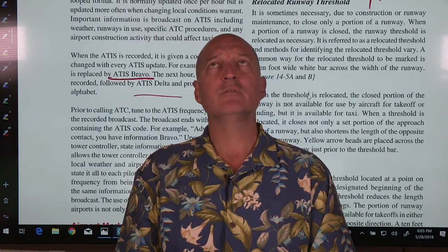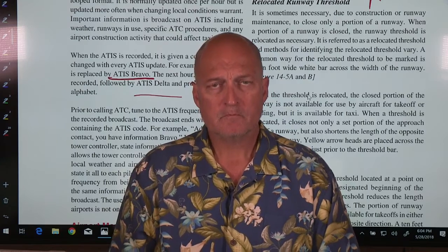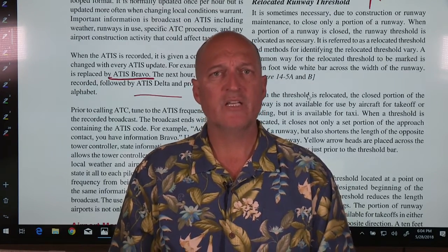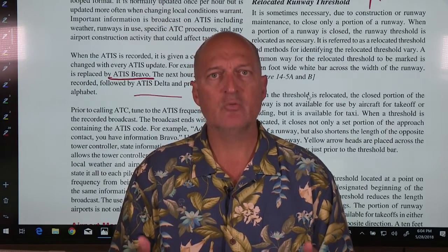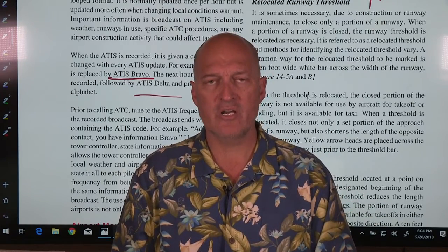I think it's 121.9. And you'd let them know, Aspen ground, Diamond Star 141 Hotel Lima at the North Tie-Down area, ready to taxi with Bravo. And you let them know, because that way they know that you have the most current information.